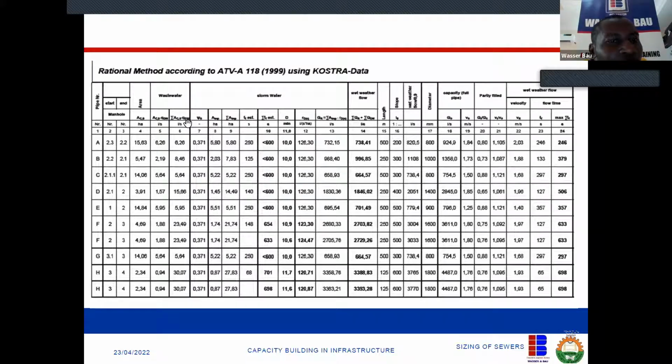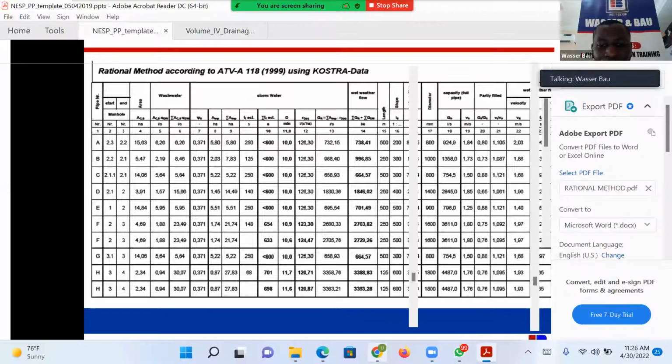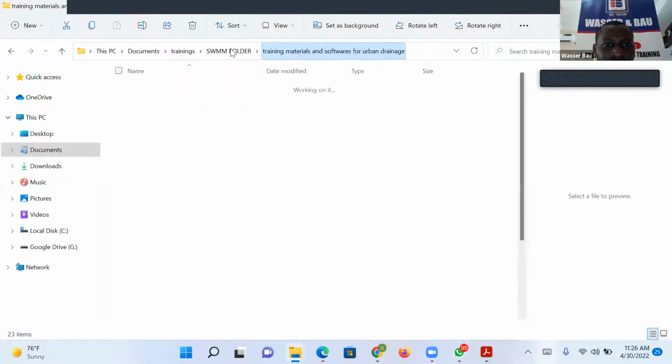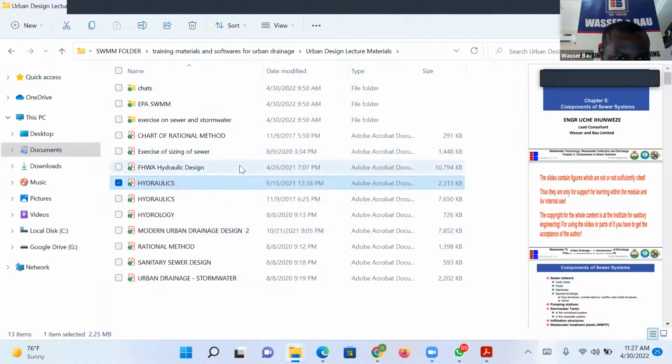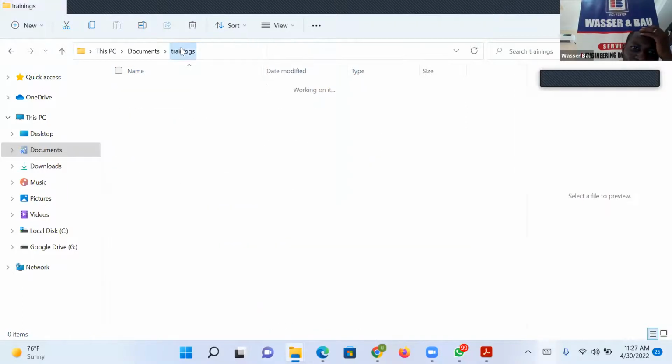So if you now come here, you now do what we did last time in our water reticulation. For this one, let's assume I'm using a circular pipe, which of course is what I should use. It's pipe A. What's the size of pipe A? Pipe A is 6.26. I will introduce us to new charts soon. But let's first maintain our water reticulation chart, because this is an underground thing, so it will work. Circular pipe, underground will work, PVC pipe. Are you with me? Go to our charts. There it is. If you can't find it, just go to the water reticulation chart, the same chart, the nomogram.